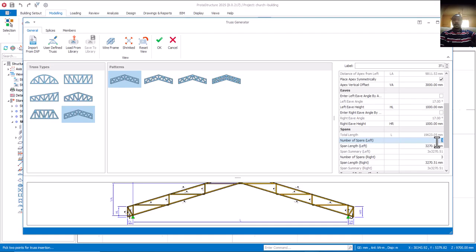So whichever one. So now I'm going to increase this one to, let's say, 7, and let me click somewhere else. So when it's 7, can you see it has increased? The number of supports, diagonals and vertical, have increased. And then if you now look at it, you have 1400 and this. So I want to make it 8 on 8. Let me see. 8 is now 1002. Is okay? So if I make it 9, what do we have? Okay, 1009, which is okay. Distance, which is okay, 1000. So I'll also come here now and put a 9. Okay, click here again. So can you see what I have now?